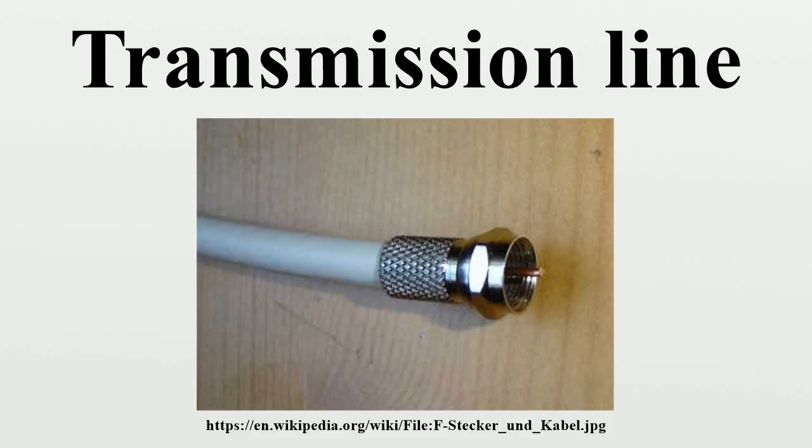Stripline. A stripline circuit uses a flat strip of metal which is sandwiched between two parallel ground planes. The insulating material of the substrate forms a dielectric. The width of the strip, the thickness of the substrate and the relative permittivity of the substrate determine the characteristic impedance of the strip, which is a transmission line.